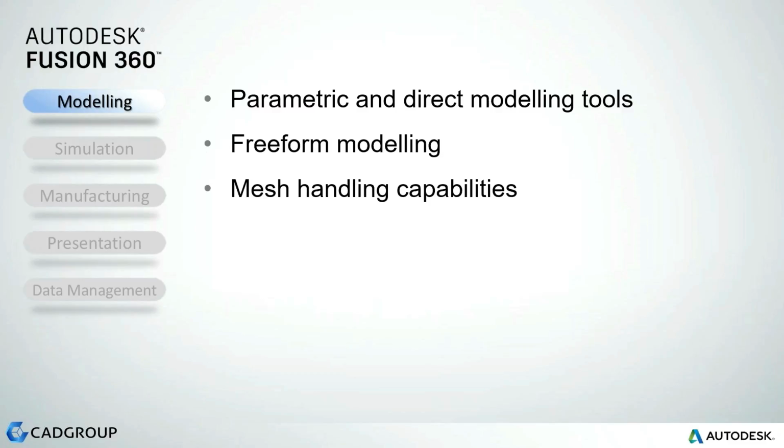Fusion 360 also allows us to bring in OBJ and STL files from 3D scanners. If you have any experience in 3D scanning, when you scan something, you more often than not need to make edits and repairs to the meshes, and Fusion 360 has those tools. Fusion 360 is not only a part modeler, but also an assembly modeler, which means that you can bring parts together and use joints to simulate motion and create motion studies to create a basic kinematic analysis.